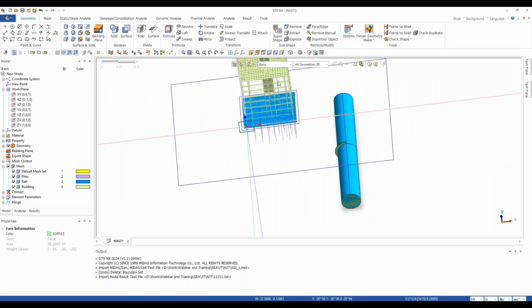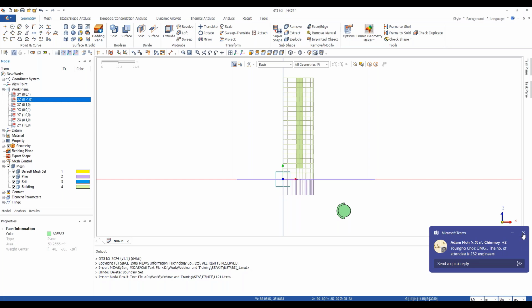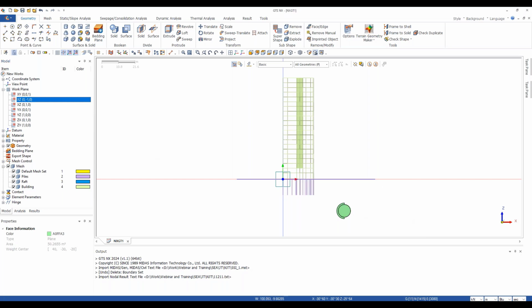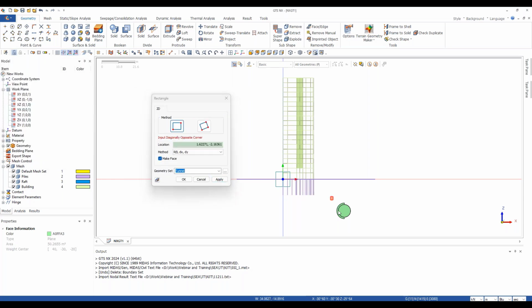What we will do is again go to the front view, because the tunneling is carried out in excavation stages. Suppose 2 meter, for example, let's say 2 meter. So we need to divide the solid in 2 meter stages so that excavation can be carried out in sequence. So for that, I'll just define a surface. We can call it a cutting plane. You can say this as tunnel only, no issues.